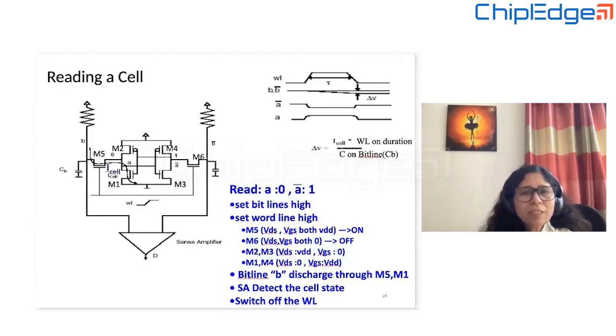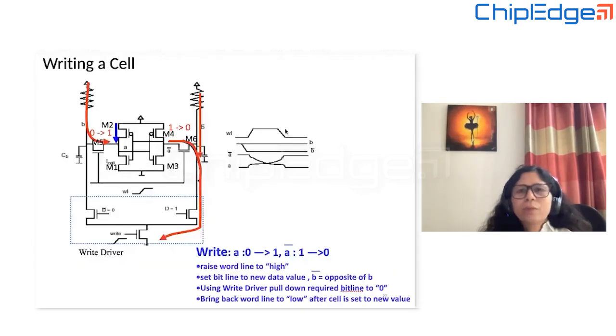And as far as timing is concerned, sometimes between designers, terminology becomes our day-to-day language. So sometimes when we say write margin, we talk about this margin: the word line going off while my internal nodes were flipped. How much margin I was having in terms of timing, when it comes to picoseconds, we talk about as the write margin time, between the bit line and internal nodes getting flipped and the word line going off. So do I have a margin here or not? Is my word line going off just when the internal node was flipping? If that is the case, then my margin is bad.